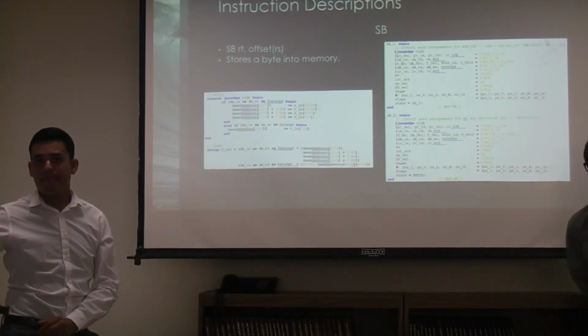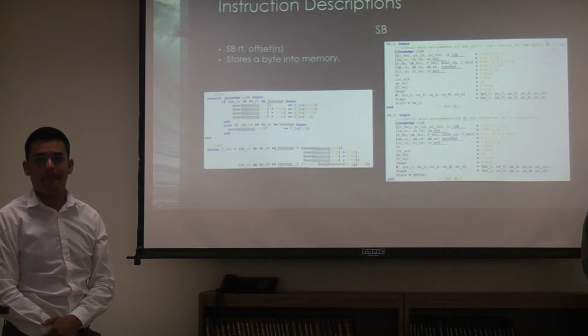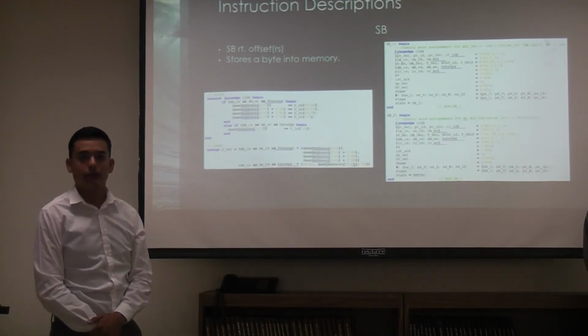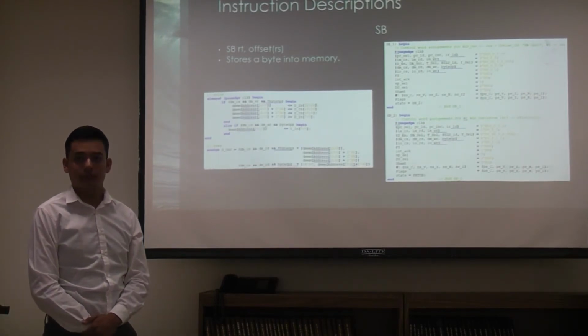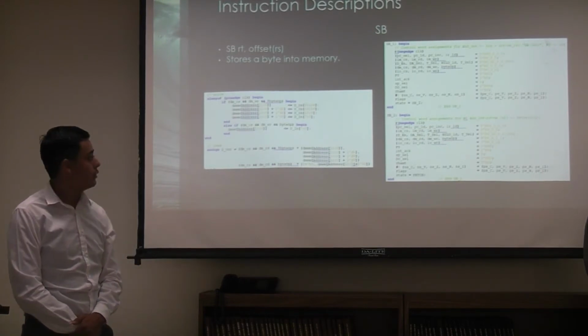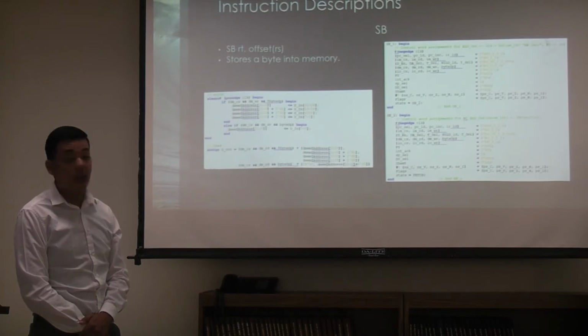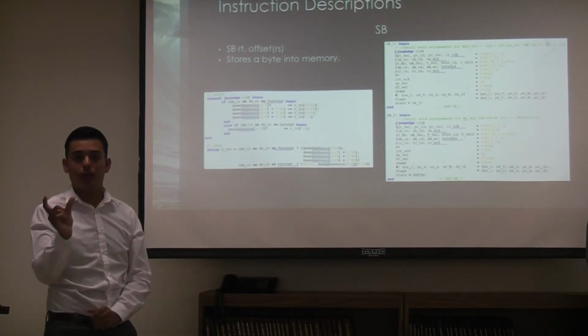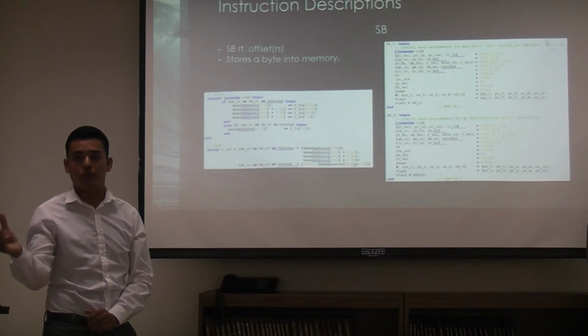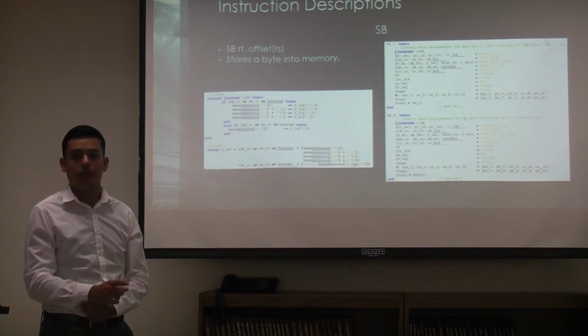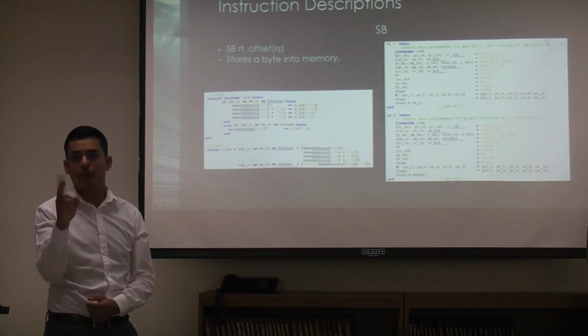So I have a question. Just to clarify, you're storing 1 byte, it's going out to an address, and so you are storing that byte to that address? Yes. Not address plus 3 or anything like that? And then the operand, this byte op, is that a new input to the memory? Yes, that is a new input. So that's a control word stating if it's a regular store or a store byte. 1 bit. Just 1 bit, okay. So we only have those two different stores and loads.